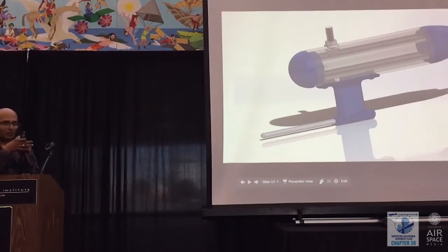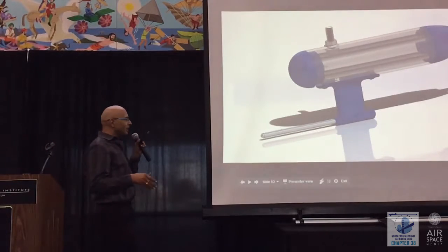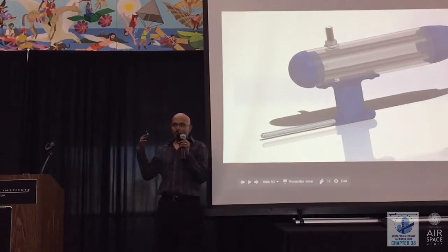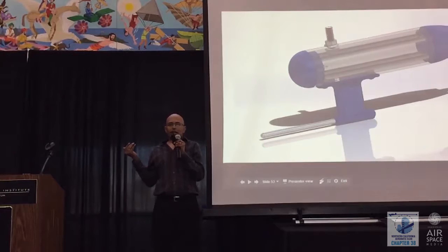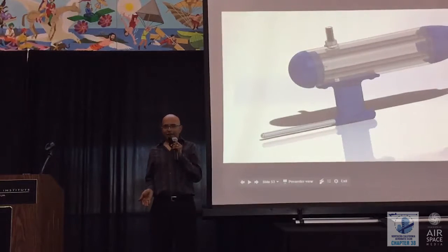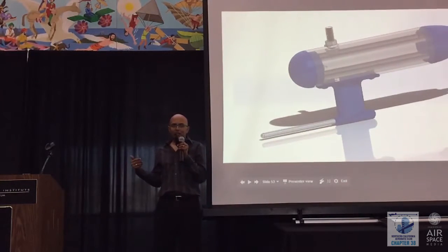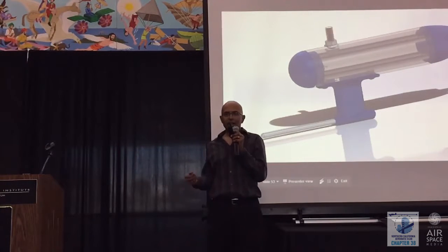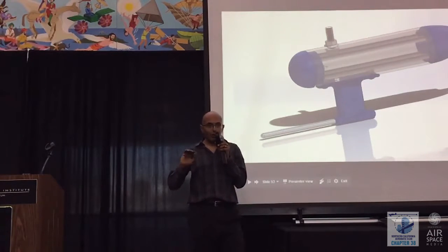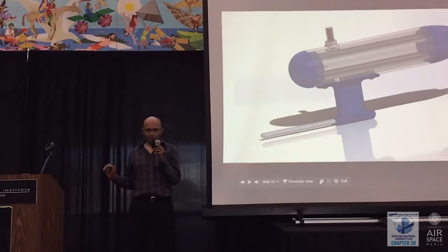So the probe that we're trying to build is something that is simple enough that someone can stick on the strut of their aircraft and not have to talk to the feds. And so that means basically make it work and look like a GoPro camera. Make it battery powered, make it independent, make it talk wirelessly to whatever it is you put in the cockpit, and just avoid regulations as much as possible.